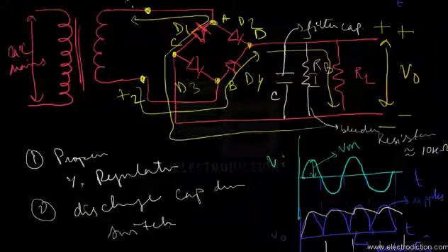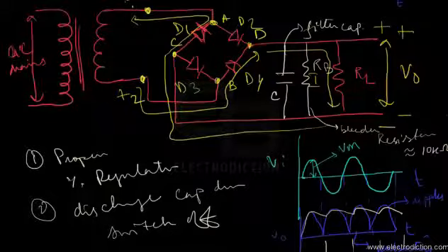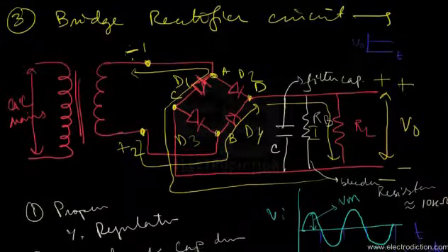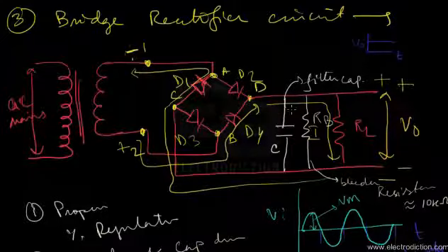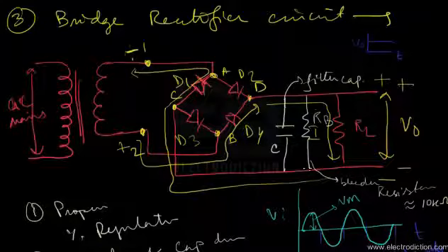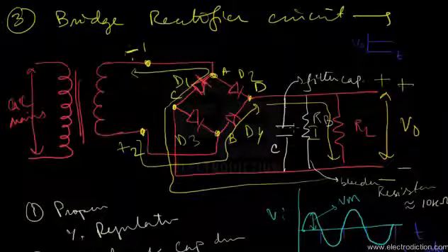Whenever the rectifier circuit is switched off and not working, all the charge stored in the capacitor is drained out by the bleeder resistance. That helps to remove the residual charges stored in the filter capacitor, and thereby increases its life as there is no overloading of the capacitor. That way the bleeder resistance helps us.